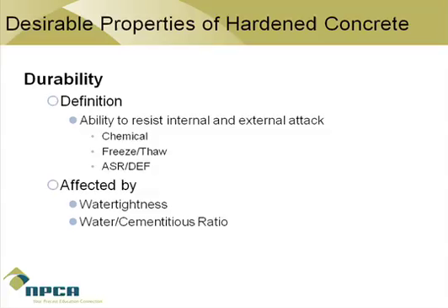Durability is also defined as the ability to resist internal and external attack from things like chemical attacks, freeze-thaw cycles, alkali silica reaction, ASR, and delayed ettringite formation, DEF. Concrete mixtures can be altered using admixtures, supplemental cementitious materials, or lowering the water-cementitious ratio to make them more durable to their destined environment.